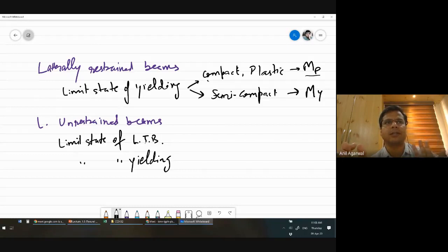Depending on whether the beam is bending in the minor axis, or whether the beam cross section is a hollow cross section instead of an open cross section, and depending on what cross section it is and what the distance between the lateral supports is, there may be a possibility where you can rule out the chances of lateral torsional buckling, and you just need to consider yielding.